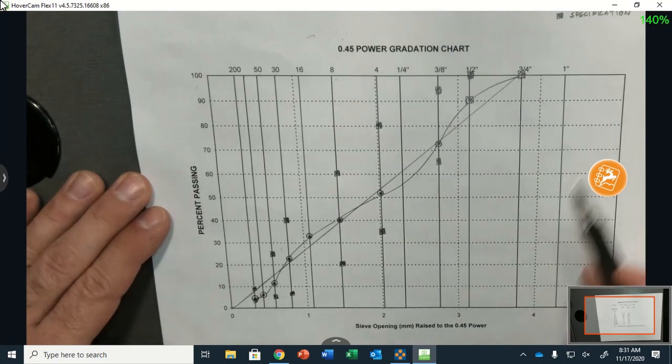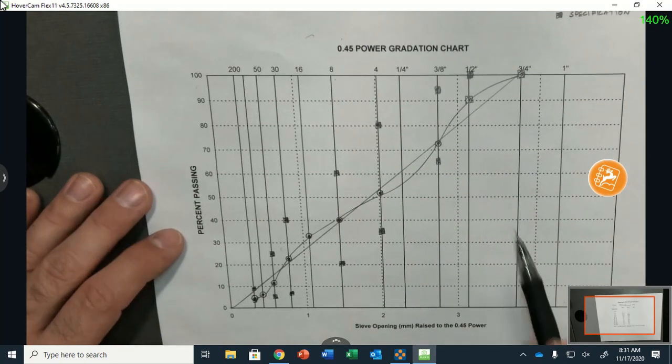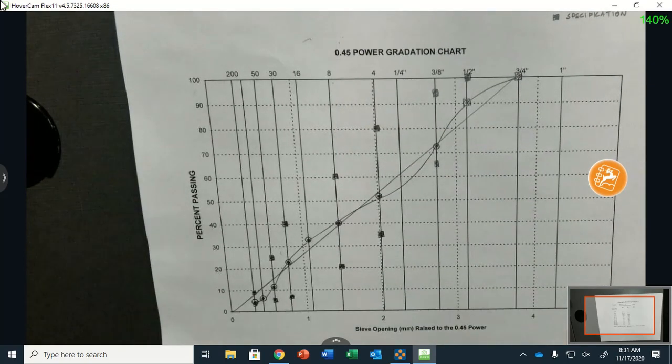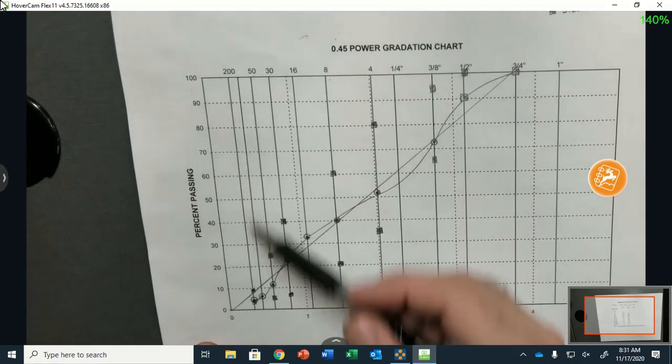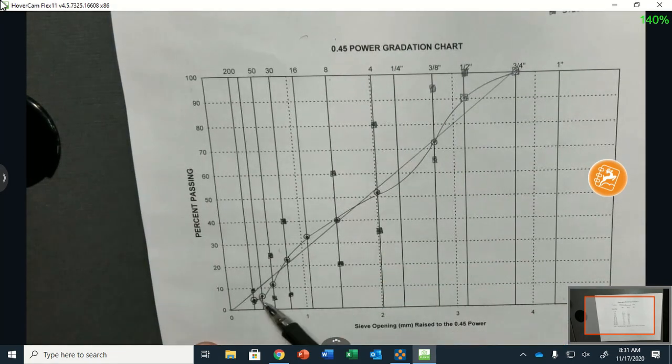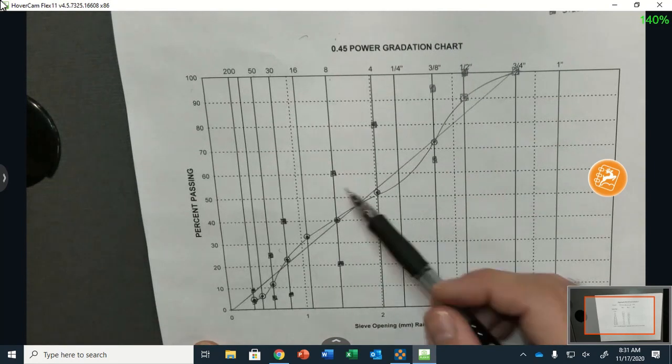okay, so one, they call these control charts, okay? So as McKeefrey and Sons is producing Northeast Asphalt, with aggregate, they're going to be running a gradation, and they're actually going to have a spreadsheet on each sieve. They're going to graph these, right?